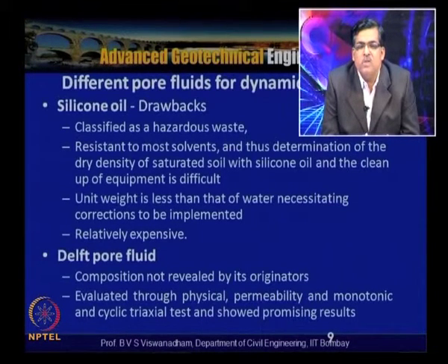And some laboratories actually have their own trademark pore fluids. One example is Technical University Delft, the Netherlands. The composition is not known, but it was evaluated through physical permeability and monotonic and cyclic triaxial tests, and it is said that the Delft pore fluid fulfills the required qualities of an ideal pore fluid.